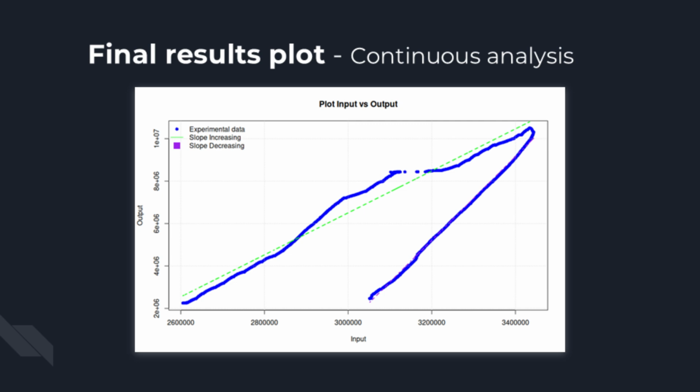Here we can see the results from a continuous test. The graph shows a significant amount of hysteresis, but most of it is due to the unintended movement of the mechanism caused by the incorrectly machined V-groove. This makes it difficult to isolate and evaluate the intrinsic hysteresis of the mechanism itself. Another important observation is the slope of the curve. Ideally, the forward and return paths should have the same slope. However, in our case, the slope during the forward motion is about half of what it should be. This is because the input force, combined with the elastic force of the system, caused an unintended displacement of the mechanism, affecting the expected behavior.